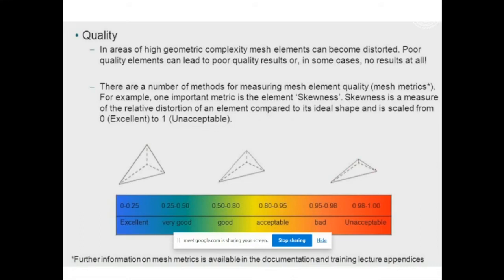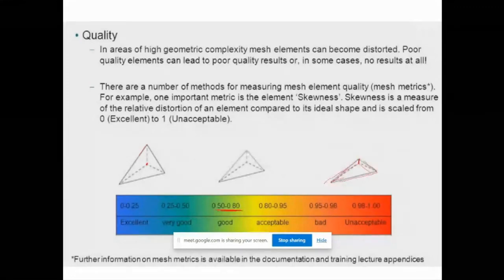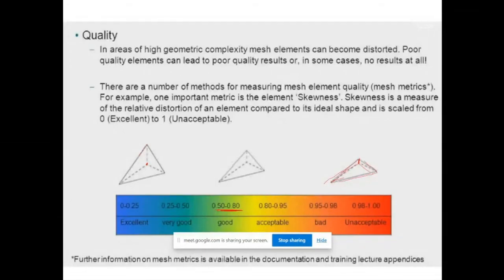So once you are doing the meshing, the quality is very much important. Here we are talking about the skewness. This is good, something in this range. This skewness is very bad. So this length is very much less than these three lengths. So sometimes there is an error in the meshing, so you have to be more cautious there, that you should make a good quality mesh.